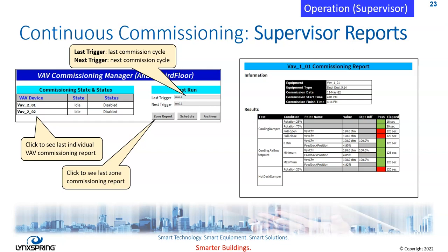For each test, a number of measurements are taken every 5 seconds. If 12 continuous samples are taken without too much variance, the value is stored and presented here. The set point difference that you see is how far from set point the measurement was for the test. Red-green indicators show the success or failure of a test, and the elapsed time is the amount of time required to start and complete a single test.